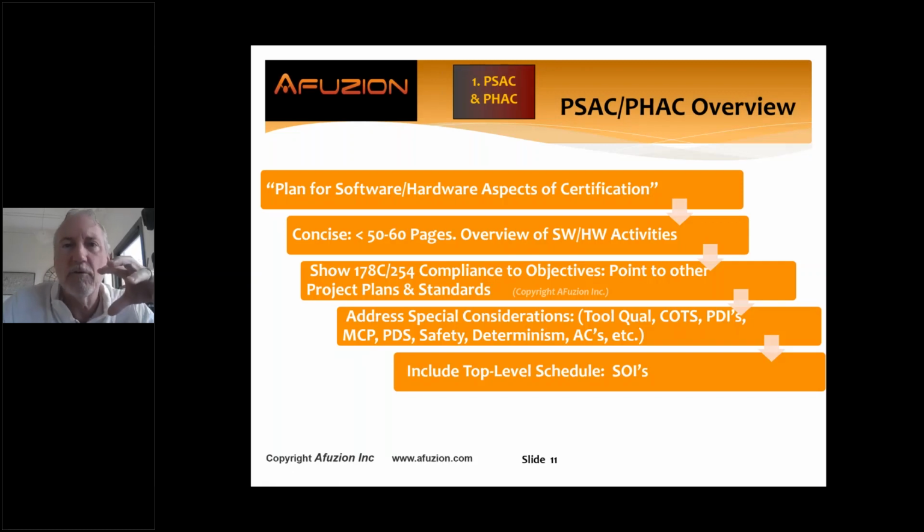Folks, if you have configurable software, you maximize reusability. Instead of 71 objectives for DAL-A software, you have 2. Ooh, think of that. But you have a little more work to do because you have to demonstrate you understand those configurations. What's the minimum and maximum range? What are the requirements for each parameter data item? Who reviewed it? Who traced it? They're high-level requirements because they pertain to hardware. They're stored external to the executable. That's a hardware-software interface. How did you test it? Did you cover all the parameters? Are they safe?